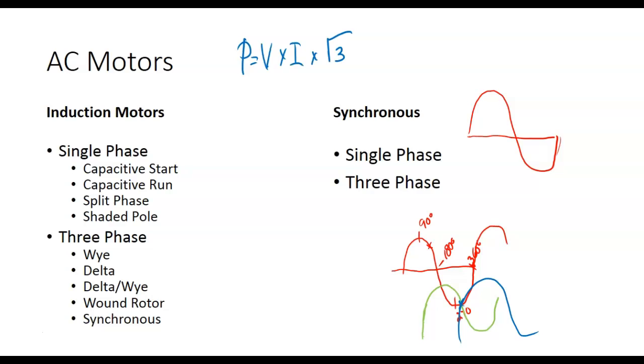So what we'll do is we'll kick it out. It's got a centrifugal switch on it, and we'll kick it out as soon as it starts coming up to speed. But the run torque, for the size of the motor, is not as good as we could get. We could get more torque from a smaller motor if we left the capacitor in there all the time.